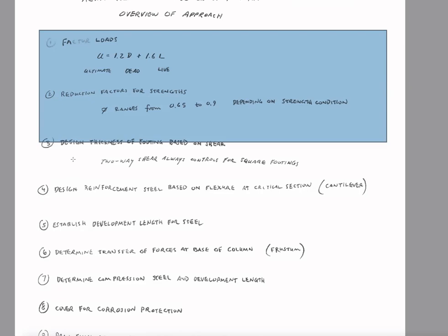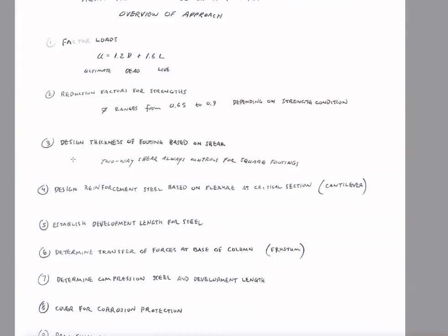We're using a working stress design for the soil part, where we just apply a single factor of safety at the end. And that's how the geotech stuff is handled. Whereas the structure stuff has this going on, where you're both inflating the load and reducing the strength. And that is in disguise a factor of safety, a rather refined one. It's in a sense more refined than just applying a 3 at the end of the problem.